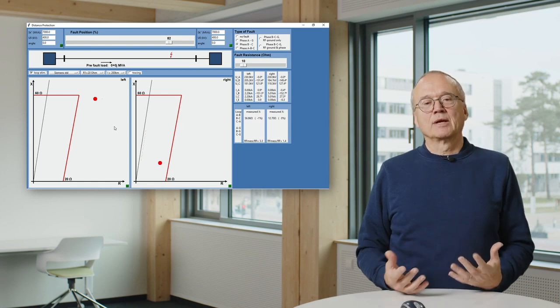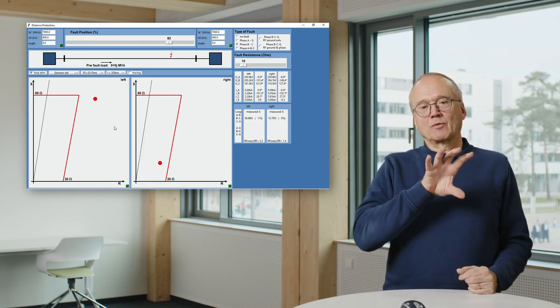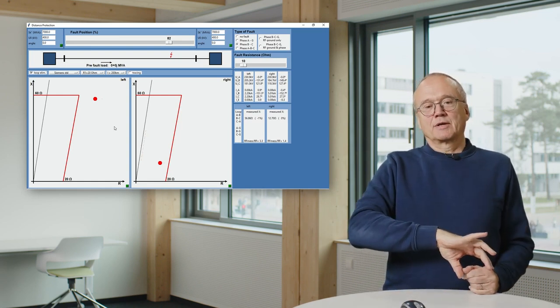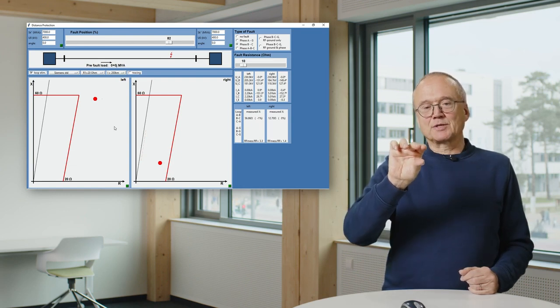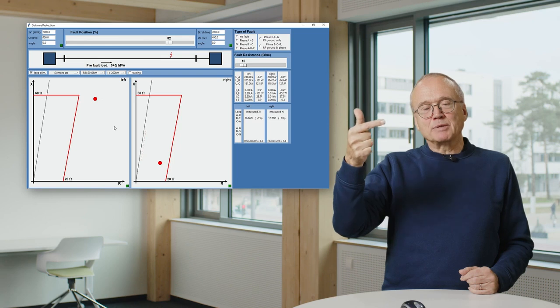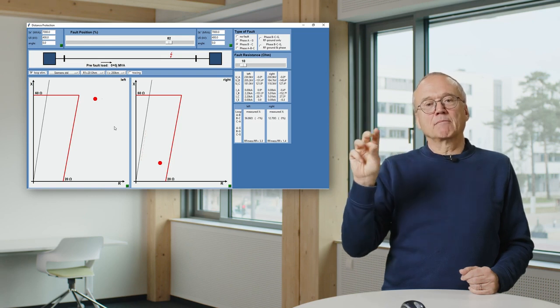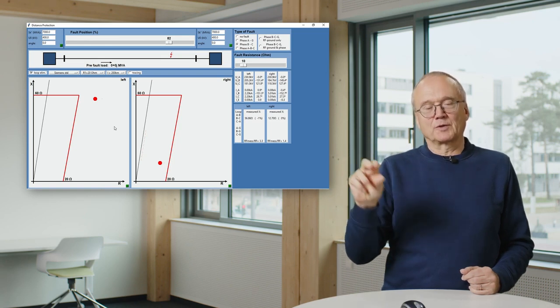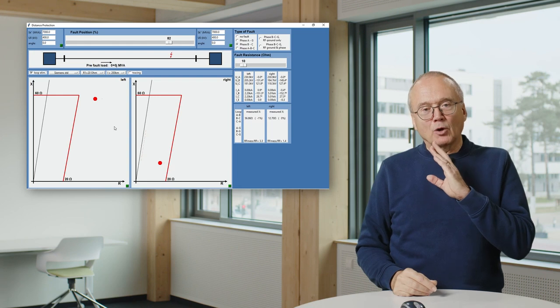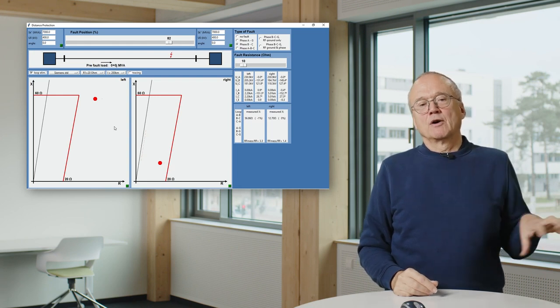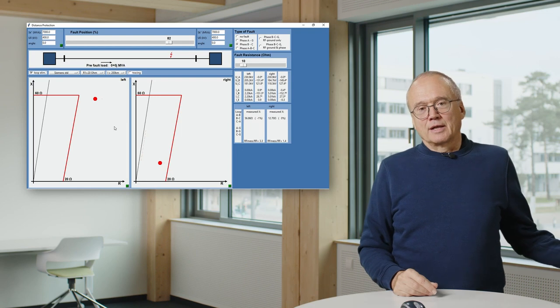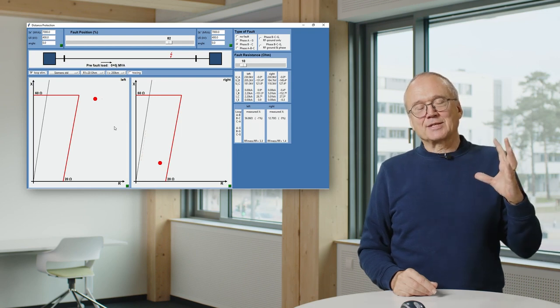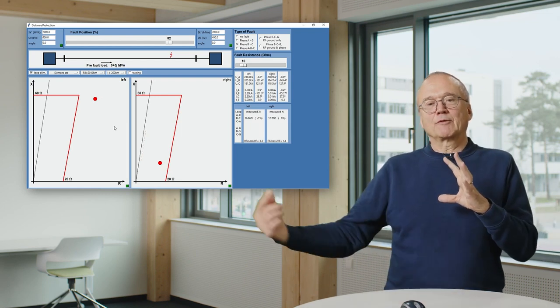Why is this? This is because, remember, what we measure is the impedance of the part of line plus fault resistance plus IB divided by IA multiplied with the fault resistance. If we have a fault at that point, for the left relay, the current it sees is lower than from the other side.